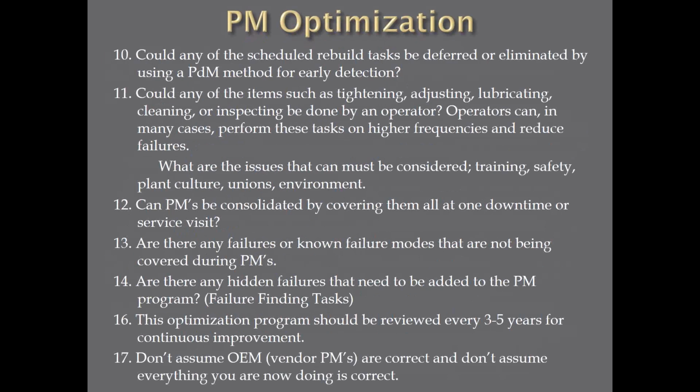It said, could any of the scheduled rebuild tasks be deferred or eliminated by using a PDM method? As you start using these small handheld vibration tools, thermographic cameras, we go out and check a bearing with an ultrasonic tool. Do we want to come back the very next day and do an actual physical hands-on PM task? A lot of times your PDM programs are going to eliminate some of your PMs.